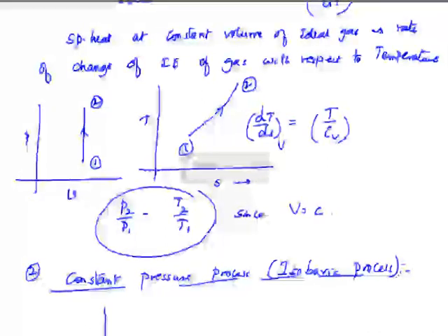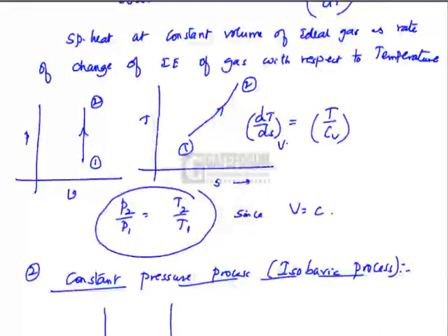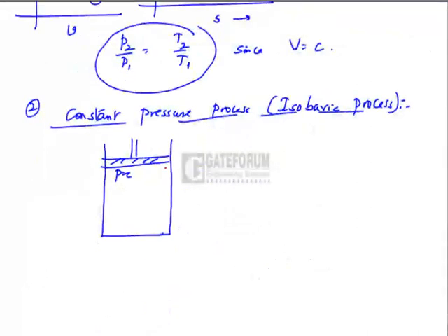The gas should be considered in a piston cylinder arrangement, because while heating the gas, the pressure might increase. To keep the pressure constant, the gas must be allowed to expand. That is, it must be able to do work on the surroundings by pushing the piston upwards.